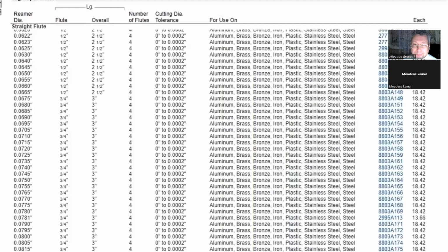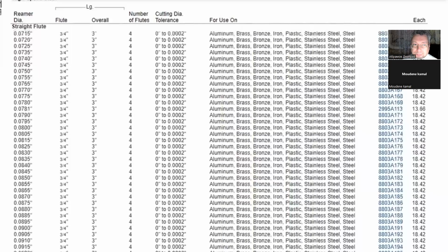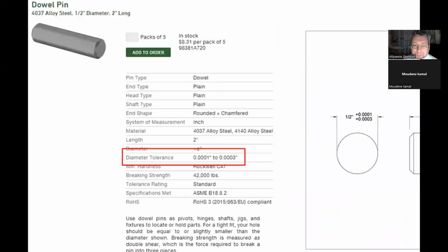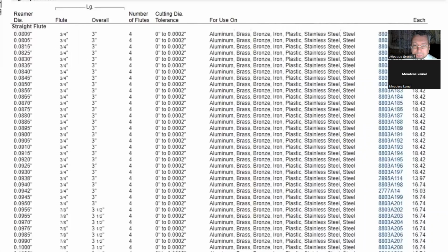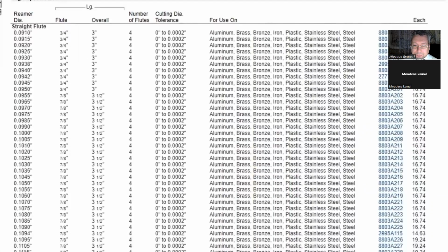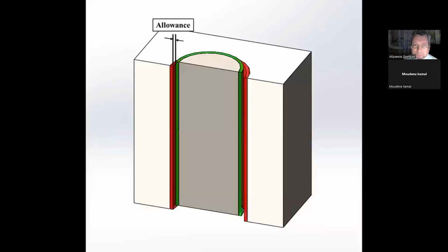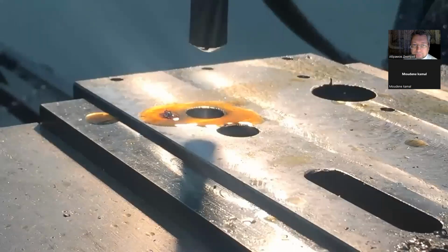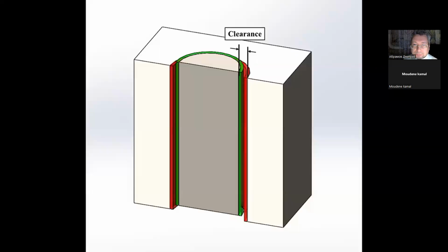So the challenge is now to decide what size reamer to use to make sure that all the dowel pins fit properly. If you know the tolerance range you can expect from your reamer, and you know the tolerances of the dowel pins, you can choose a reamer size where the smallest hole the reamer can cut still has space for the largest dowel pin. This is called the allowance, and is typically something you choose. You're allowing, say, 25 microns of space between the largest dowel pin and the smallest reamed hole. Because there will be other smaller pins, and your reamer will sometimes cut larger holes, you may also find yourself cutting the largest possible hole for the smallest possible pin. The extra space on top of the allowance is called the clearance.